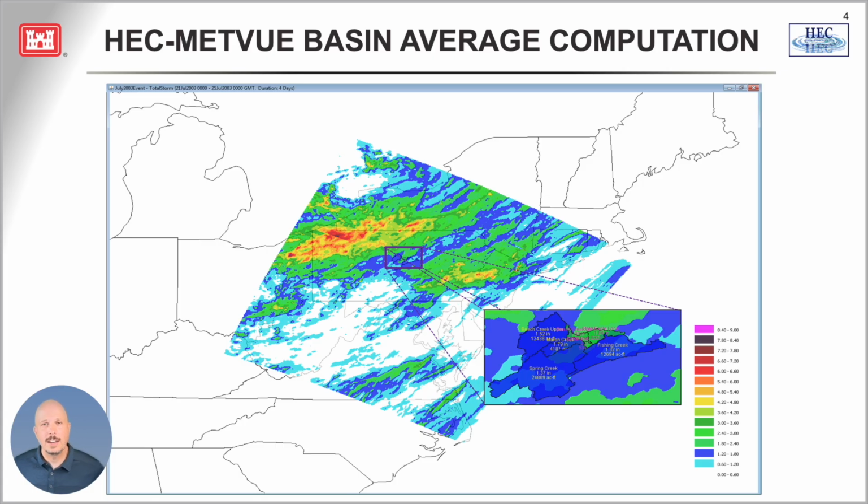Additionally, one can save basin average time series per polygon from a basin average shapefile. So for any designated basin average shapefile, the Save Time Series tool can be used interactively to write out basin average time series to DSS. And optionally, a text summary report can be written out as well.